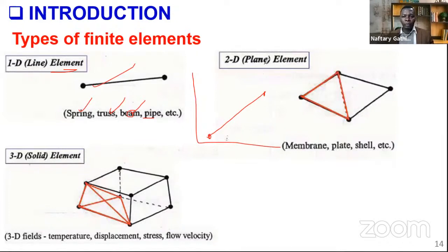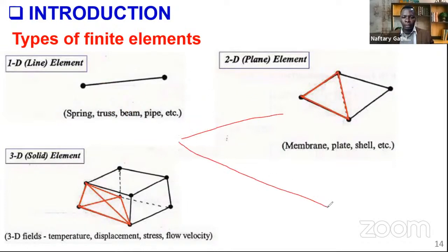In cases where we talk of 2D, consider a slab. This is a typical slab, and you want to analyze it using the finite element method. When we are talking of a beam or a frame, like the one in the Abaqus documentation, we can analyze it as a truss or a plane frame, where each line element carries axial load, a 1D element, pinned.